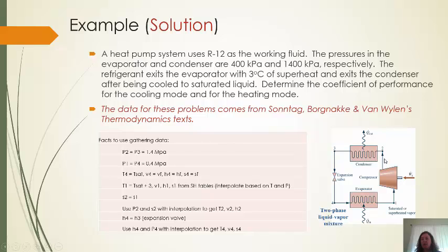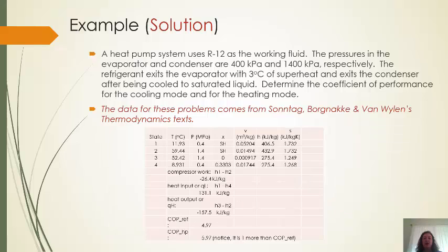Work is going to be performed in the compressor. I need to find those 2 delta H's, but I have this pressure and temperature defined awkwardly, but it's defined. And here I know the temperature, the pressure, and I will be able to finish all of this stuff up. Okay? Oh, and constant H at the expansion valve. Forgot that one. So here's the data that I obtained.